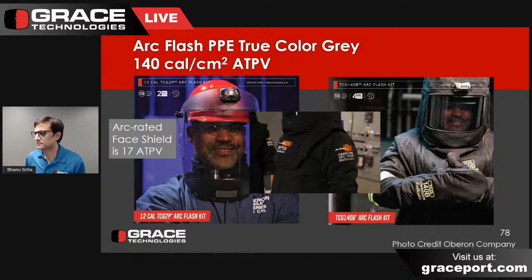So again, look at different suits. In your electrical safety program, define level 1 as everyday task wear and level 2 as an arc flash suit. And you need to look at suits that are 50. Well, I'm telling clients right now to go all the way to 100 cal. The wearability of the 100 cal is the same as a 40 cal suit now. And again, we could talk about the reasons why. Even if you stop work at 40 cals, put your workers in a 100 cal suit.